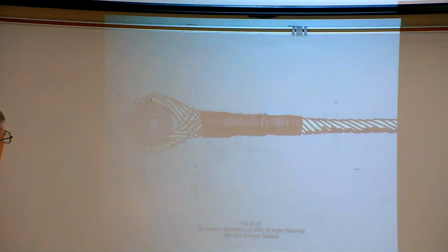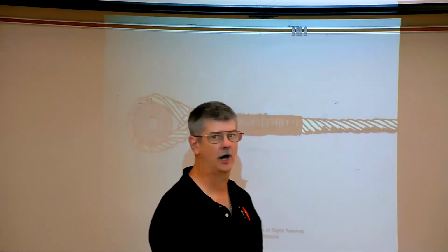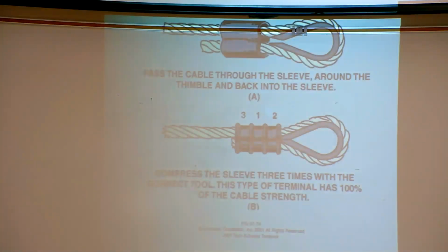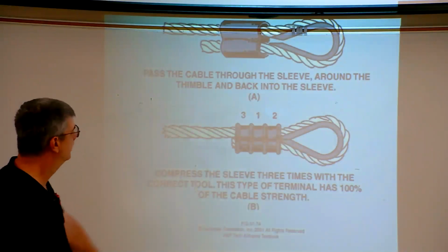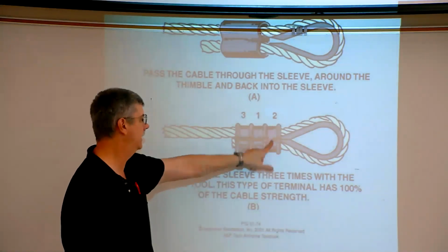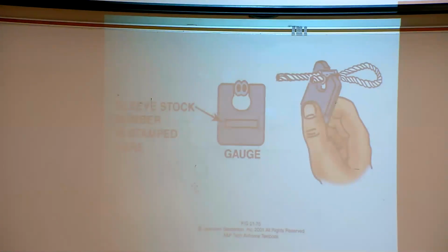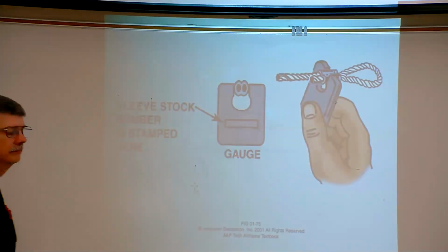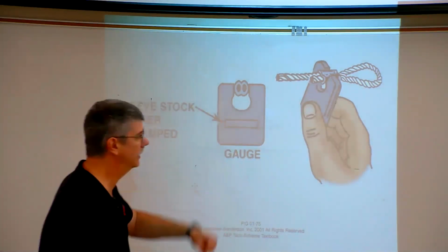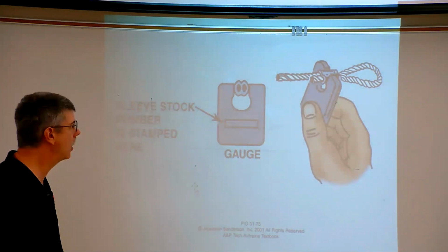I got nothing really. The type of splice that we no longer use, either the Army Navy 5-tuck splice or the Robley roll, right? When doing a Nicopress sleeve, we always want to crimp the center first, then next to the eyelet or the thimble, and then next to the tag end. To make sure that the swage has been installed properly, be it the MS or the Nicopress, we use what's called a check gauge or a no-go-go gauge.